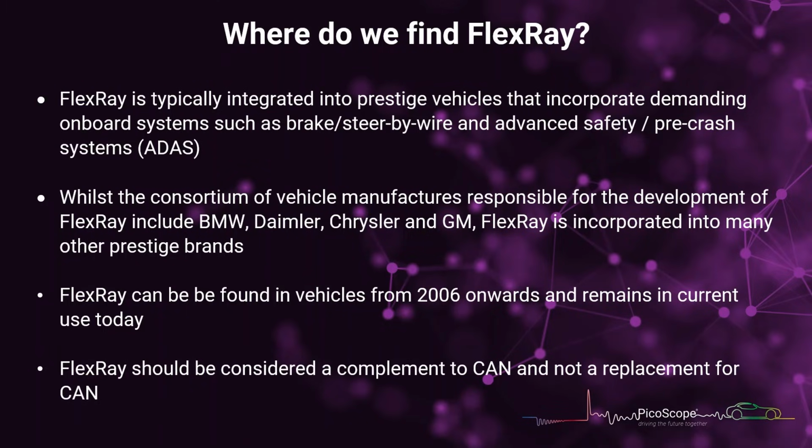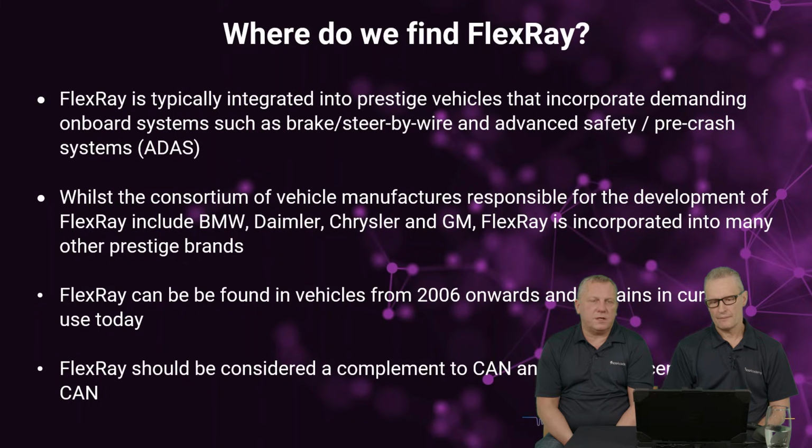And yeah, I've put this in. FlexRay should be considered a complement to CAN and not a replacement for it. Because not everything needs this speed, therefore this cost. And that's why, in the previous CAN video, I said I still see CAN continuing for many years, and that's the reason. It's going to come down to cost. The faster the network, the more it costs.